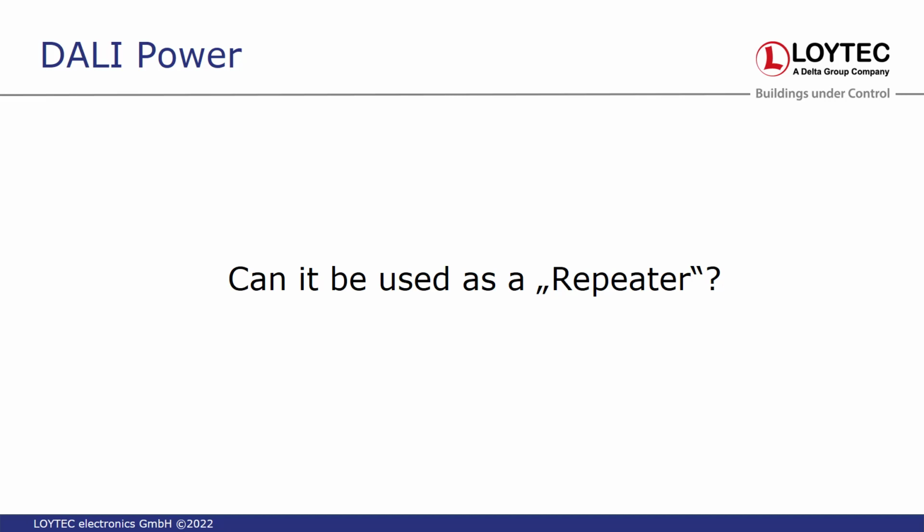But it would also introduce two power supplies on the same DALI subnet. As a repeater. You see a maximum of 2 volts. Yeah, volt drop on your run. So I'm just thinking, if it was a long run, is there a way of putting a second power supply on as a repeater?